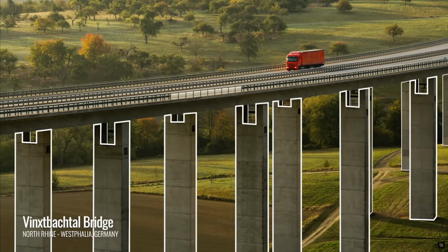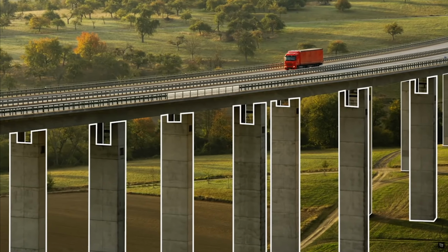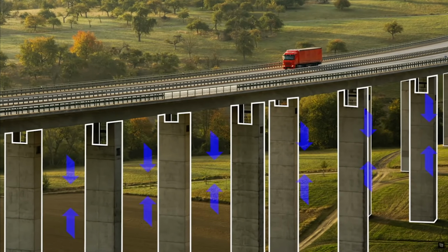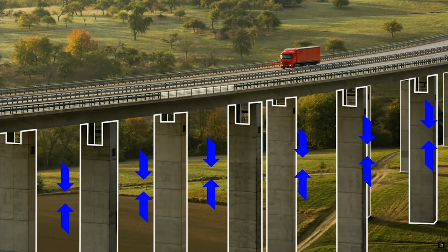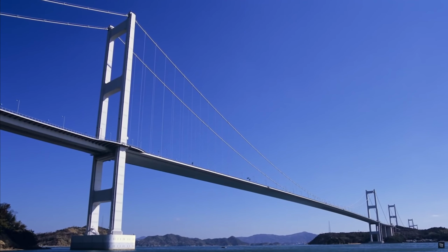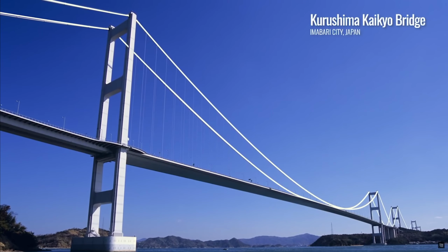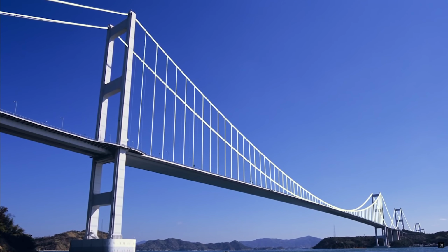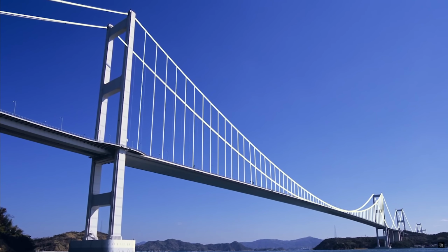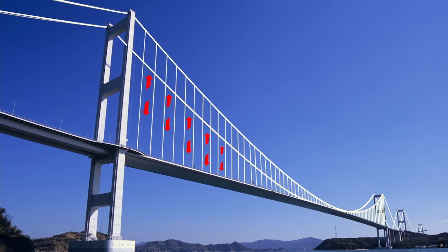An example of a component experiencing maybe just compression would be the columns. This is a part of the substructure, which is connected directly to the foundation. As loads from the beam rest on the columns, they are going to be experiencing compression, more specifically axial compression along the length of the column. Another case where tension may be the only thing, given a case of a suspension bridge. These are bridges where you see a draping cord or cable going from one support to the other, and then hanging from those draping cables are additional cables that are then attached to the deck to hold up the deck. Well, these particular cables are experiencing pure tension because it is experiencing a force that is stretching those cables.